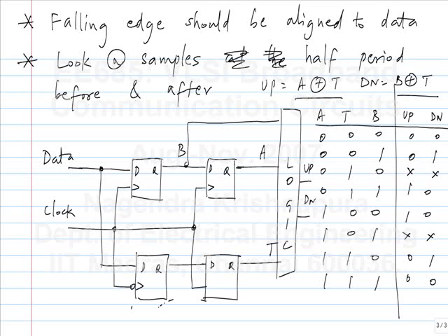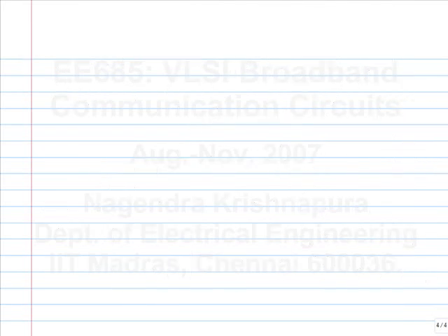So this is known as the binary phase detector or bang-bang phase detector. The term bang-bang comes from bang-bang control. If you have a binary digital control system, sometimes you do that, right? If something is too much, you just turn it off, and when it's too little, you turn it on, whatever that it is. So that's known as bang-bang control. So that's what this will be. This will just step the VCO to a higher frequency or lower frequency, depending on if the phase is retarded or advanced compared to the data phase. And it's also called Alexander phase detector because of the inventor's name.